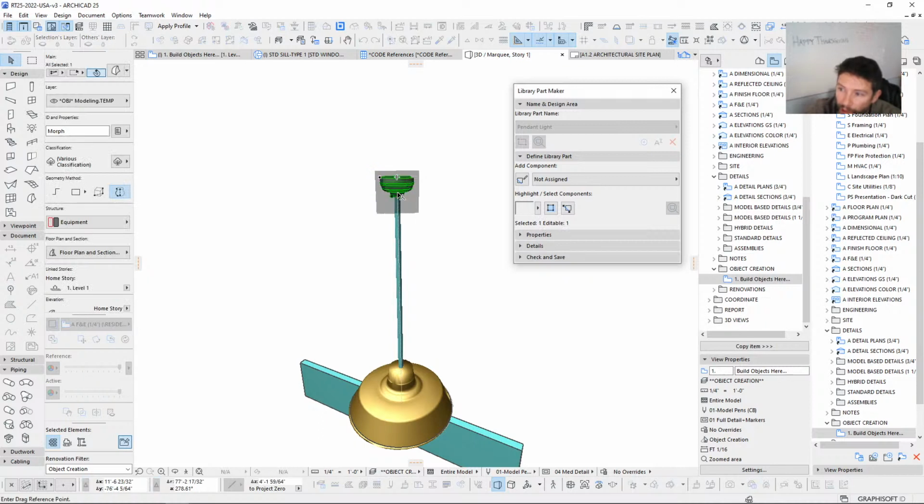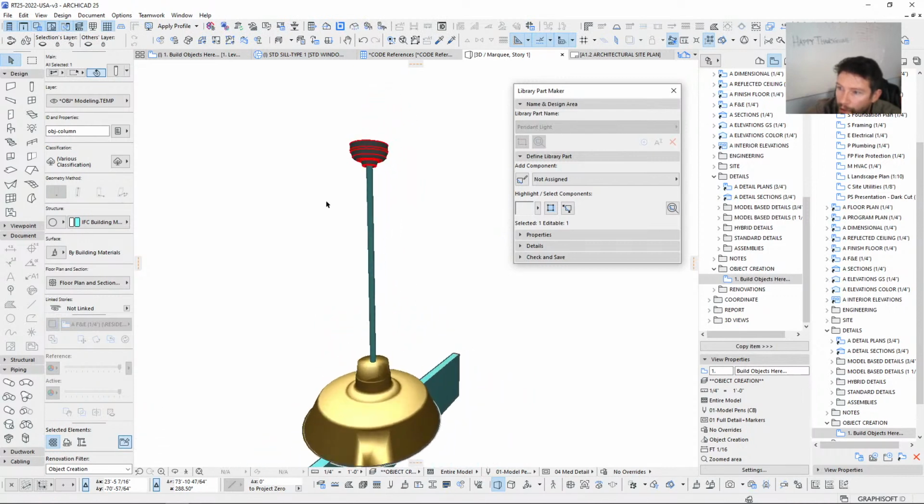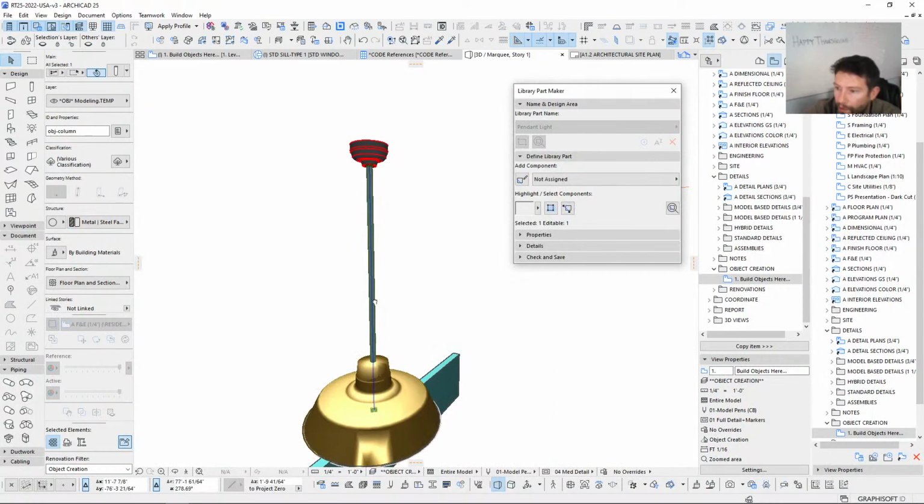Now, I'm sure there's flexibility here. Let's just set this exactly at 4 by entering into our elevation. So we're going to go 4 feet right there. And then we can just take our column. We're going to stretch this down a bit. And there we go. So finally, with our column, we're just going to set this as like a steel fabrication.